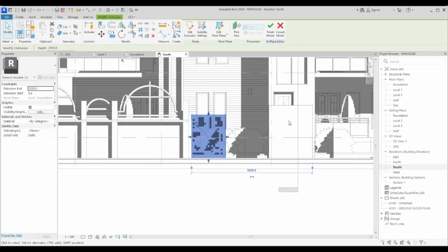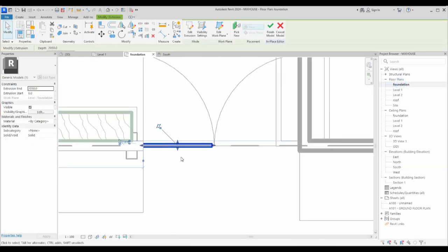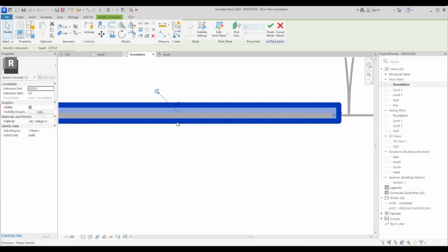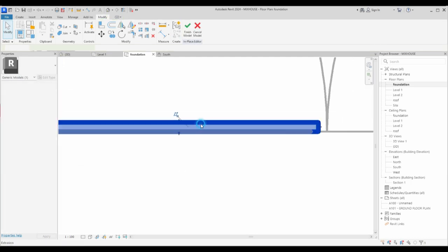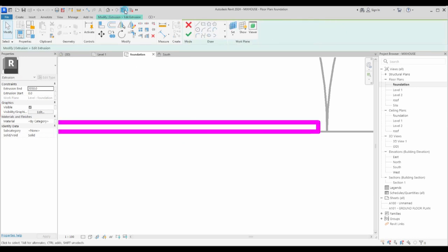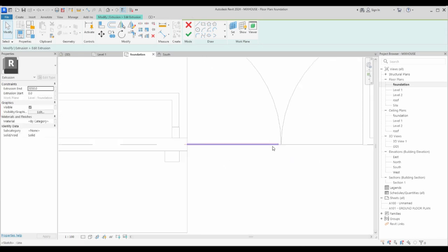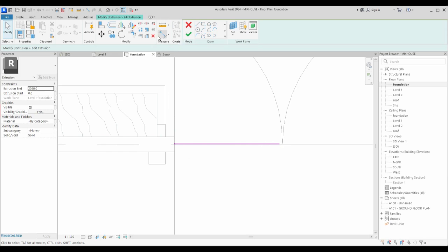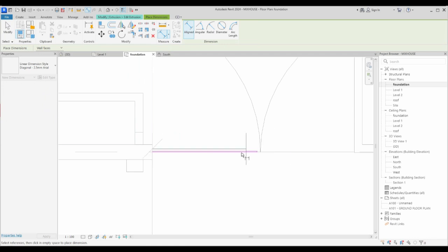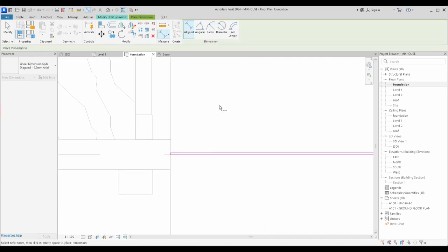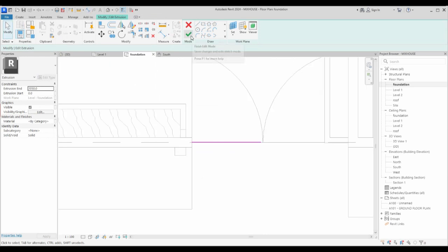So I'm going to reduce the size again. So I have to extrude, reduce the size. You can edit it again of the decline so that you see the proper dimension. So something like 15 mm is the standard. So click OK. I think that's done. So what is the total length? You check that aspect again before you proceed to your join. So here you have it as 1580, which is okay. So you select finish.